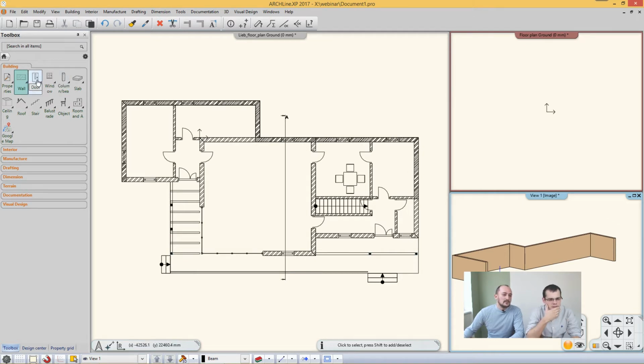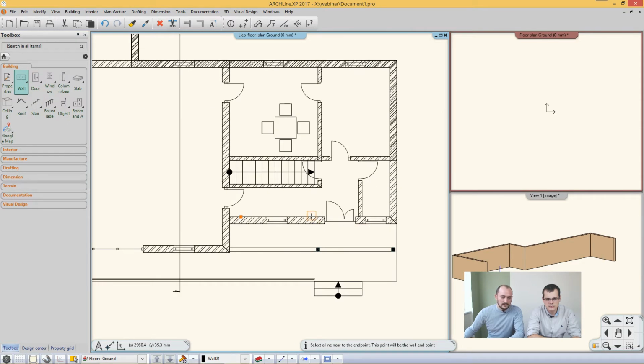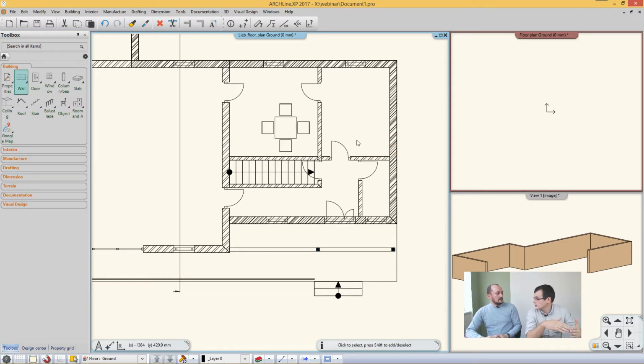So what happens if I process the walls and then later I realize that I should have created something different and I need to reconnect the walls and just create this here from here to here? Then all you need to do is either in 3D or in 2D, you just click on this L or T connection to connect those two items together, and then you will have something like that. So it basically fillets together the walls. Yes, definitely. So this is how you will go on.